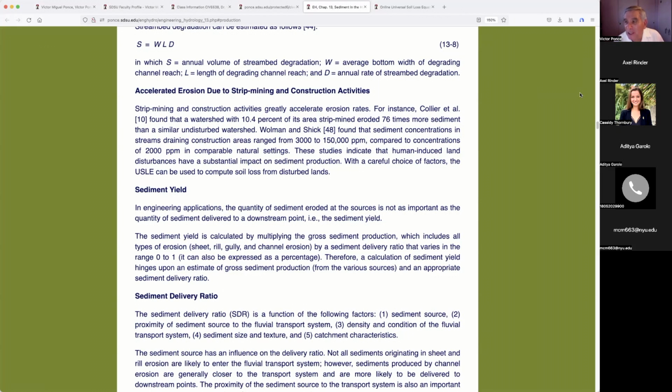So the people in Tijuana, the engineers, decided that if they had another flood, and they could not tell when, but it could be like the next 3 years, next 5 years, they were going to hold on to the sediment and let the water go by. That, of course, in retrospect, was a huge mistake. But they did it because they did not know the Lane relation. They were civil engineers, but they were not hydraulic engineers, let alone sedimentation engineers.